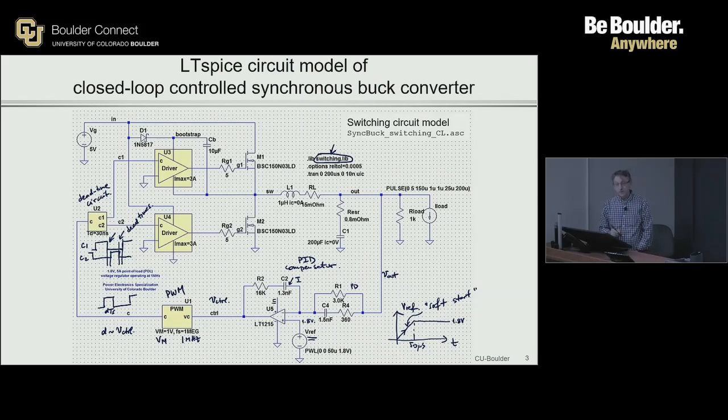All right. The dead time circuit has a parameter that lets you choose whatever dead time you like. In this particular case, we have a dead time of 30 nanoseconds. So TD is 30 nanoseconds. The way the subcircuit is constructed, it assumes the same dead time for both commutation events.